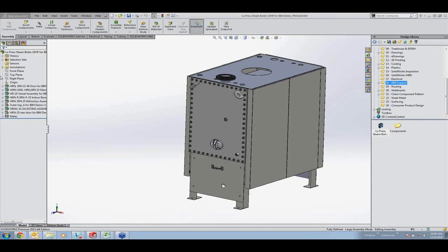Another very powerful tool is to export to DXF. Save that on the desktop there. I'm going to choose a reference point and hit accept. It shows me a little window here of what the DXF is going to look like. It's going to be printed out and used to cut fabric. Very powerful tool. All right, that is surfacing for 2015.